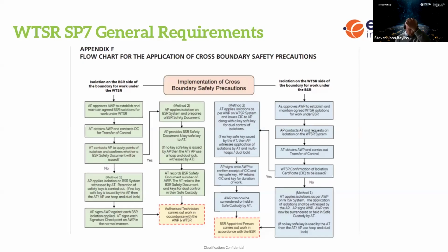If you go to the right-hand side of things, this is the blue section of the flow chart. This is covered in section 7 of the P7 document, in particular points 7.4 and 7.5. Credible scenarios for this would be a transformer inspection and HV maintenance under the boundary safety rules.